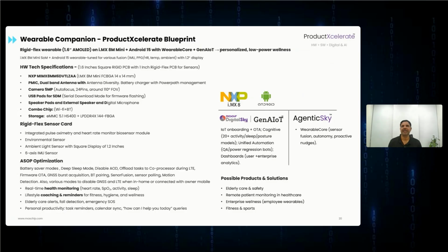This design has a few more components like PCA9450 PMIC, dual band antenna with diversity, 5MP autofocus camera, USB, SIM pads, audio interfaces, and Murata Wi-Fi plus Bluetooth combo. The design has eMMC 5.1 HS400 and LPDDR4X memory, providing a stable high-speed performance for multimedia and sensor workloads.